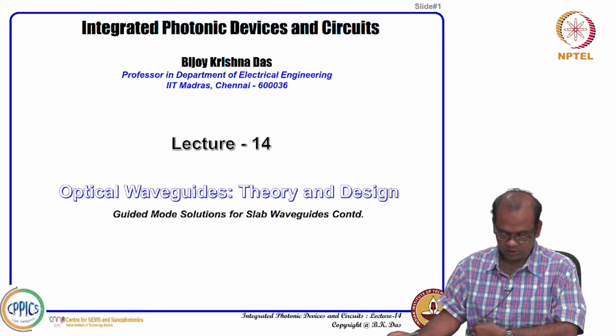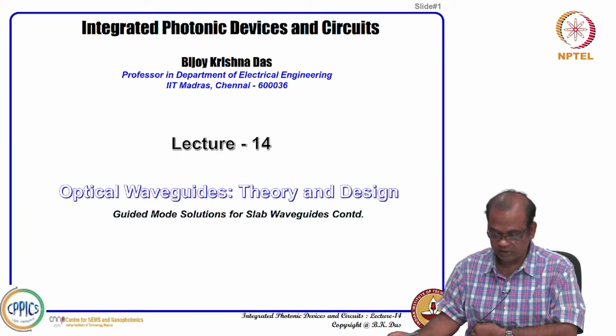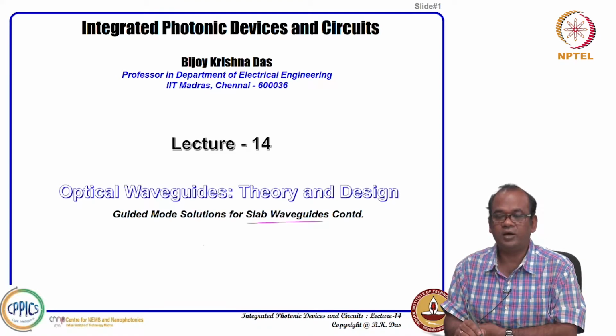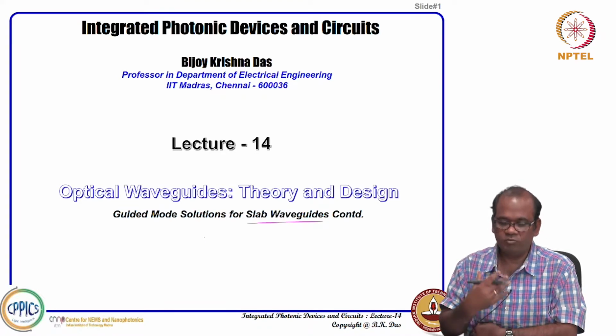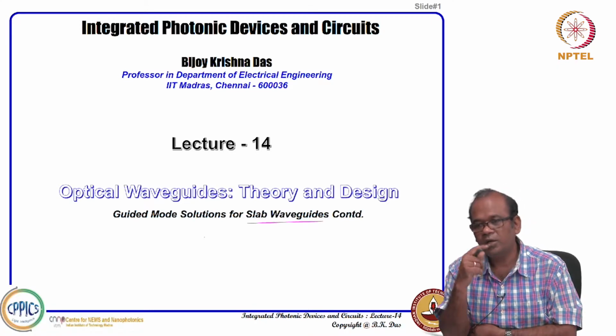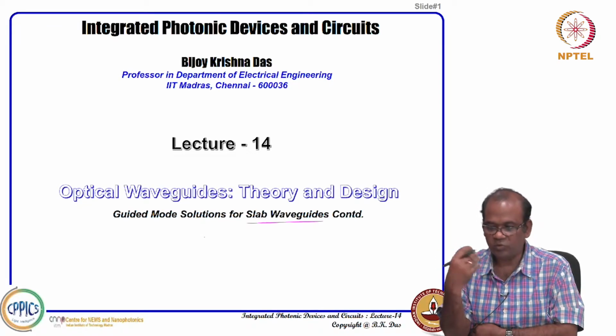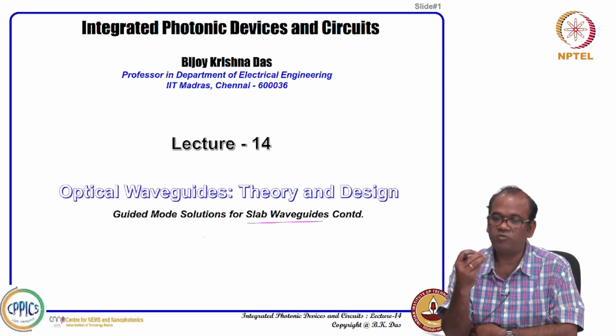We continue our optical waveguides theory and design. We have been discussing so far slab waveguides and the guided mode solutions, using different approaches. First we discussed the ray optics model, and we understood there is a limitation; up to a certain extent it is useful. Beyond that we need to solve the full vectorial wave equations, and in the last lectures we established the full vectorial wave equations starting from Maxwell's equations